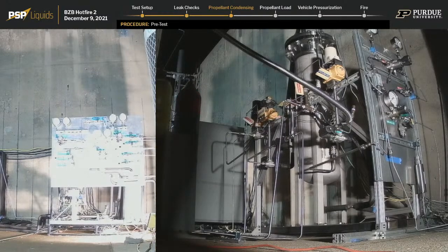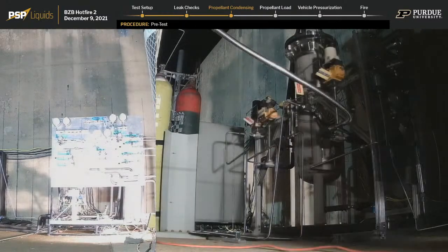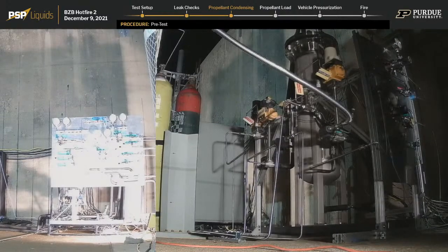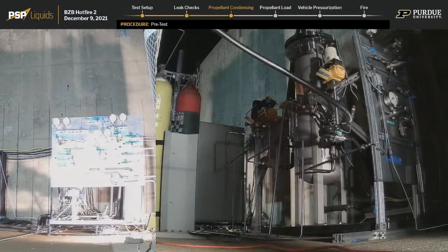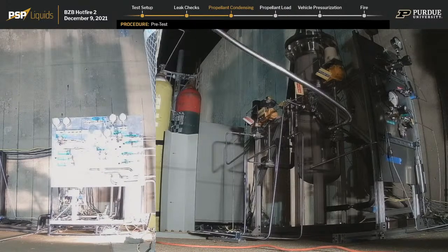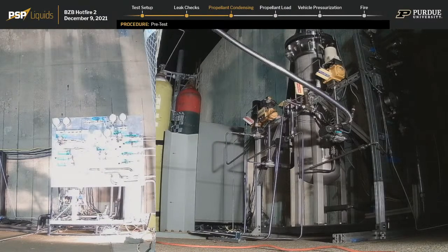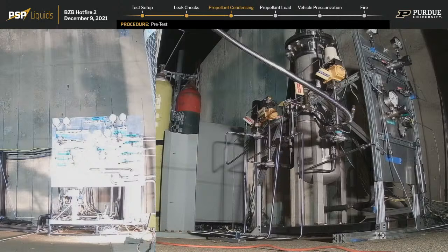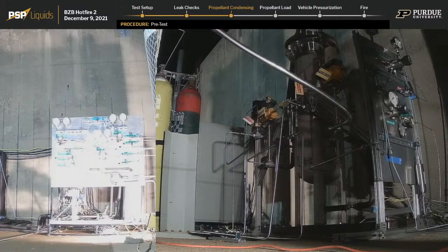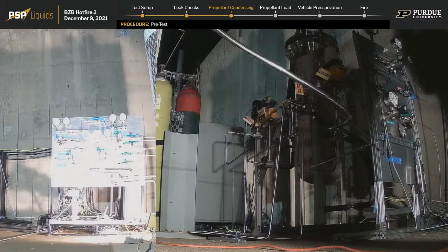This central column you see is the condenser, and as we discussed earlier, we're going to be slowly opening needle valves, and our end goal is to see liquid nitrogen flowing out of the bottom of that tube, and that will tell us we have it all chilled in, and then we'll be able to start condensing methane out of it. Yeah, so most of our procedures up to now have been leak checks. Most of the rest of these procedures should be chill in, and then after we chill everything in and start condensing, propellant load and vehicle pressurization will happen very, very quickly.